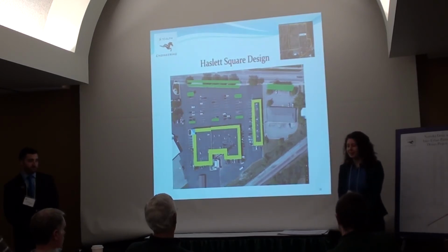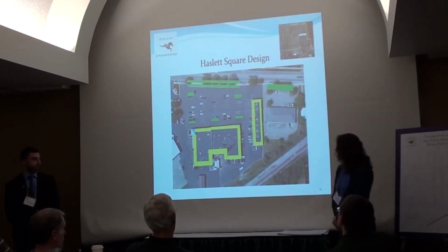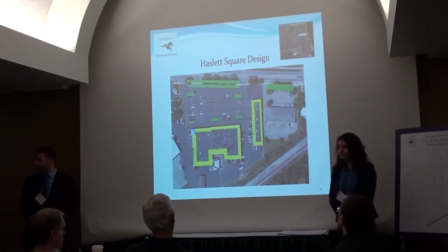I'm not sure. What I'm getting at is, what kind of water volumes have you got on top of these roofs? I have the area of the rain gardens, but... What I think you need to know as a starting point is what volume you're putting on top of this, what kind of depths you're looking at. You've got a weight associated with the water, correct?